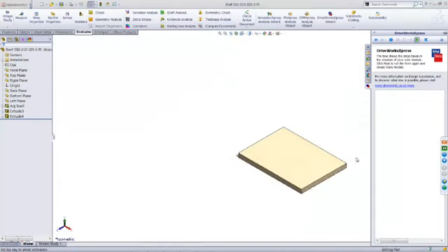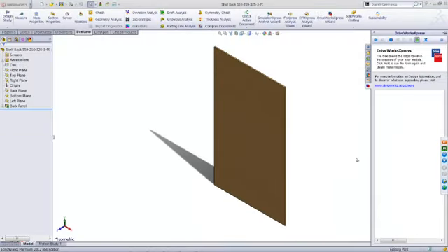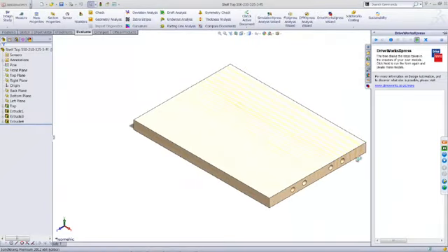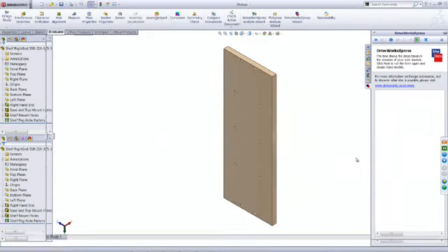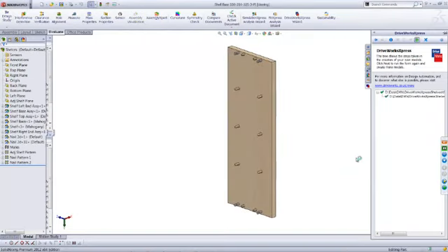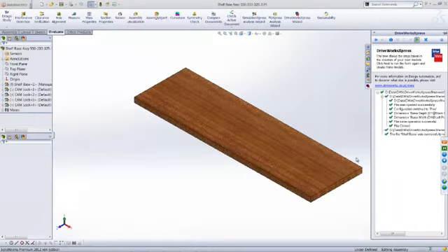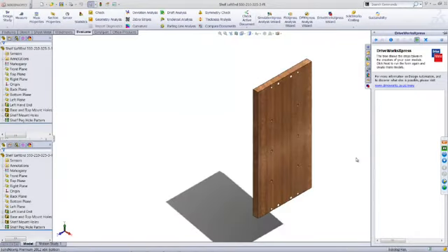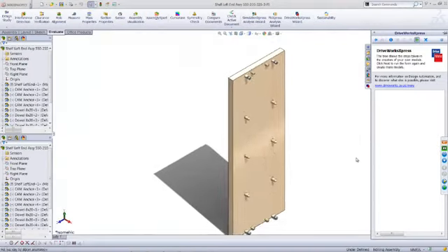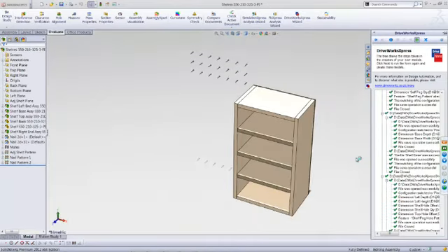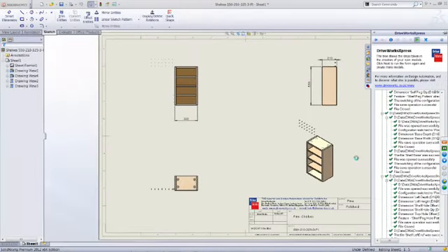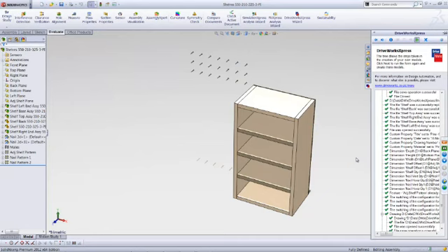Same thing again. This is another example of how you can drive your models. Now notice that even the material type can be selected and changed accordingly to the selection of the user, which is what's happening right now live, complete with all the required pins and so on. And as usual in the background, you get the drawings being updated also. So this is a very handy example, and those are the bolts and all that. And of course the bolts are now nicely placed outside so that you can actually tell how many bolts are needed. But this is your before and after. Once again, things like the file names have been updated accordingly.